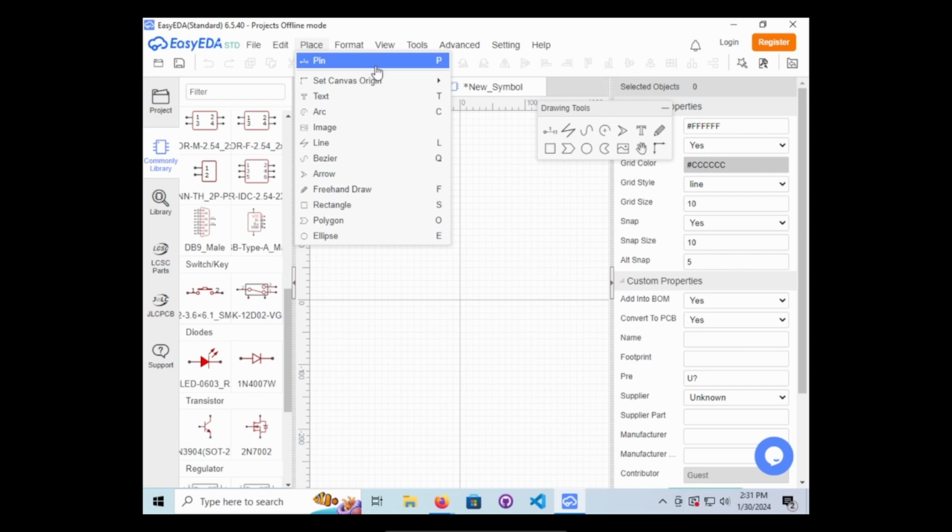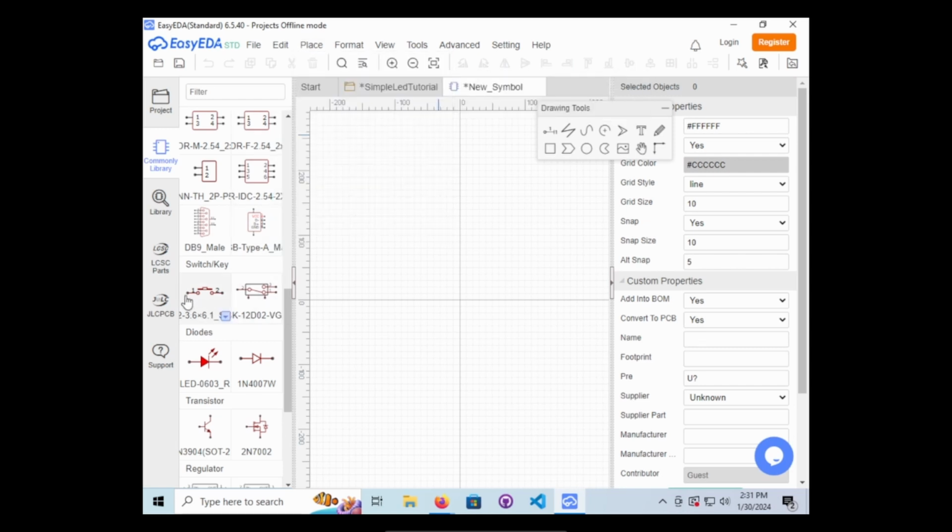Pins are how you wire up. If you look at all of these, there's a solid and an open dot, or a solid to a line. This is your pin. Pin 1, pin 2, pin 1, pin 2, pin 3. These will match your data sheets. Your data sheets can tell you which pin is which. That's extremely critical on SOTs like this. Sometimes when you start getting up there, they do some interesting things with the pinouts. So you'll want to match what they have.